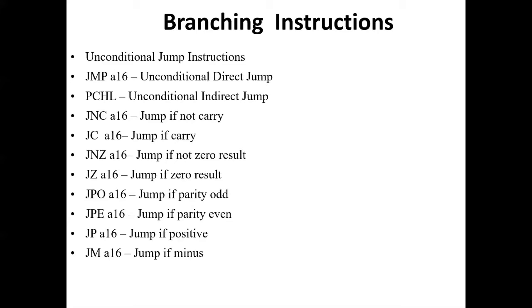In this example, after executing JMP F950H, the PC is loaded with the value F950H, overwriting the earlier value of F823H. Hence, after execution of JMP F950H, the instructions at the location F950H will be fetched and executed. Next is PCHL. PCHL is a mnemonic which stands for load PC with the contents of HL.